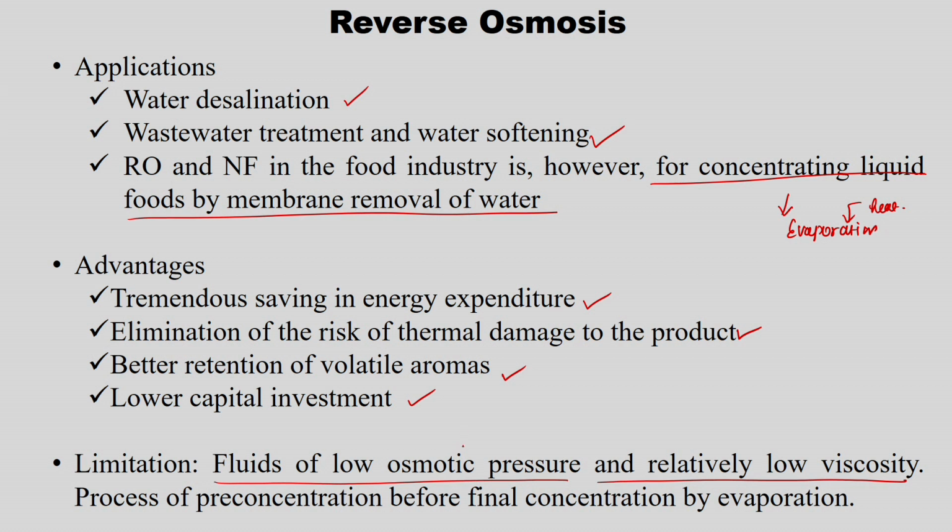So, in reverse osmosis, because you are applying the pressure against the osmotic pressure, these processes can be applied only for fluids with low osmotic pressure. That means salts, most of the time, cannot be handled, because they have a high osmotic pressure compared to other materials, and only a relatively low viscosity product can be handled.